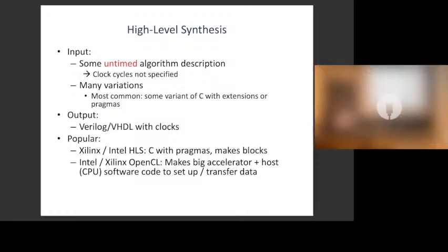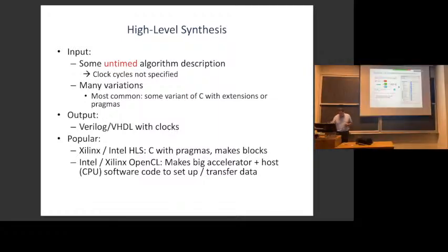This is commonly used by an important market for FPGAs, people designing signal processing algorithms. So both Xilinx, which is now AMD, and Intel have tools that can go straight from a Simulink block diagram, something like what I've shown here, to hardware, because they basically want to reduce friction for this class of people who are potential users of FPGAs. Those people don't really want to go write HDL, but they're already in Simulink modeling their system.